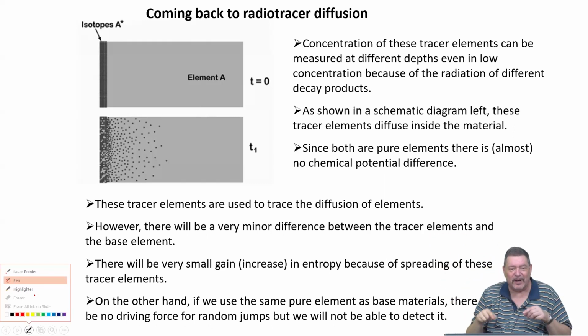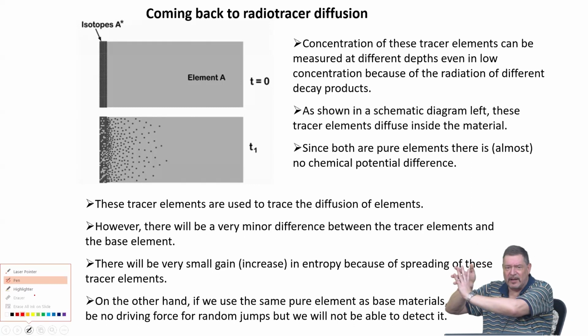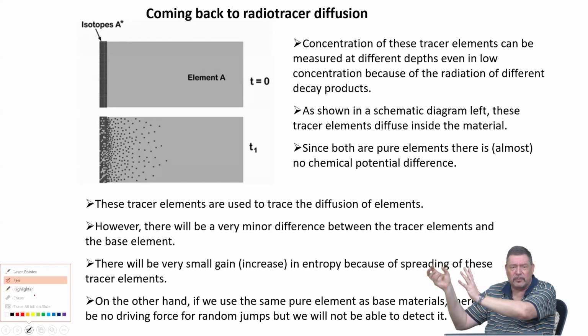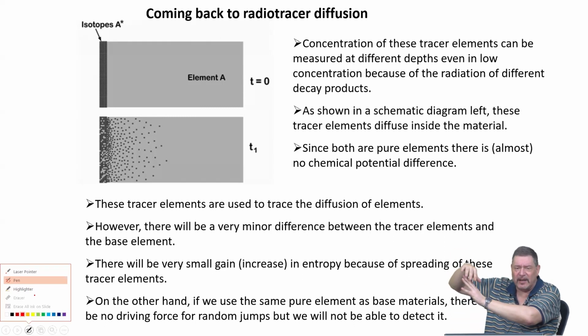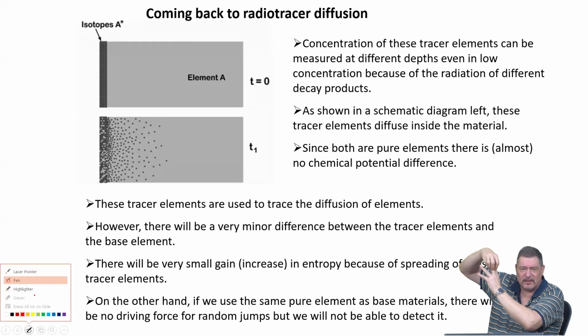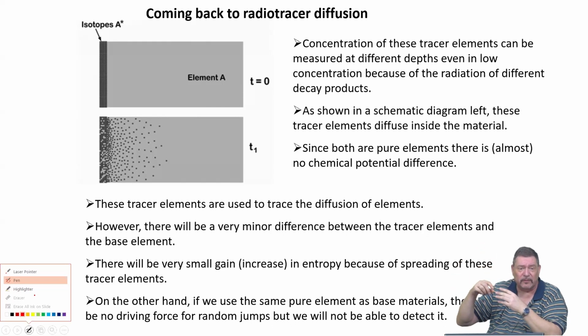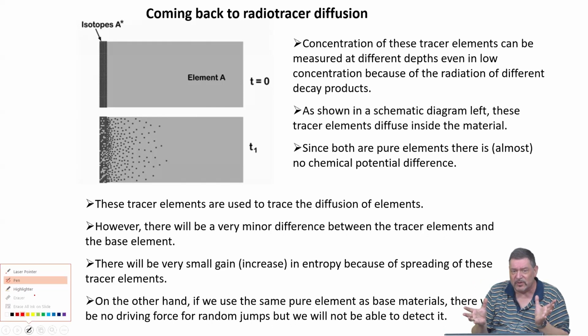In X and Y, it's delocalized because you have these multi-channel plates, which basically give you the opportunity to do the 3D reconstruction, but half of the atoms hit these grids. So they are not counted. So the counting efficiency in 3D atom probe tomography is about 50% of the atoms only.